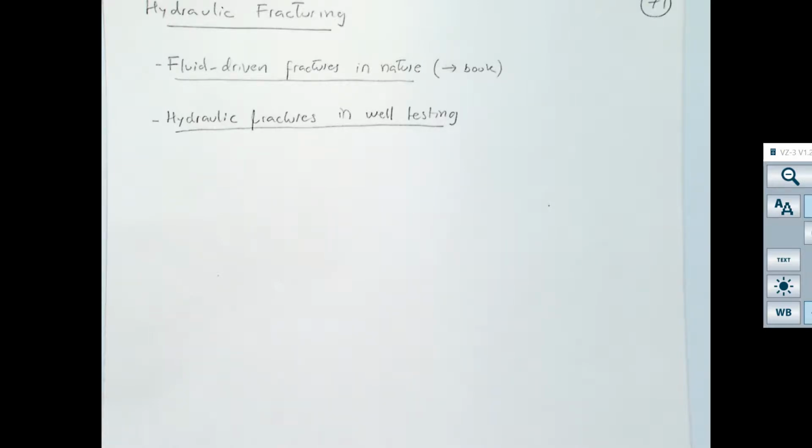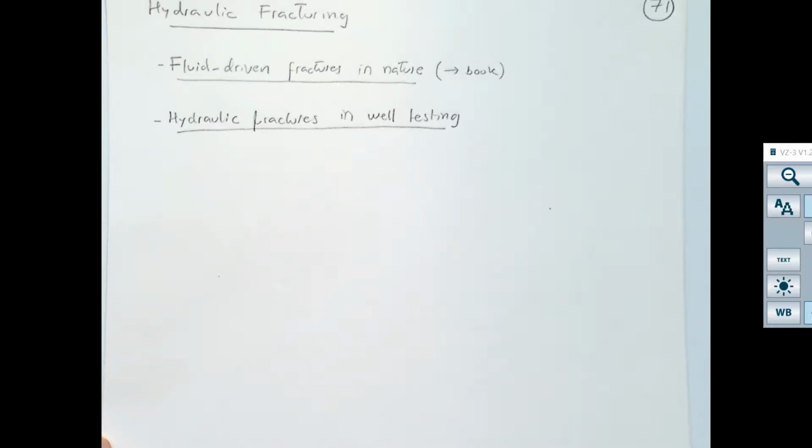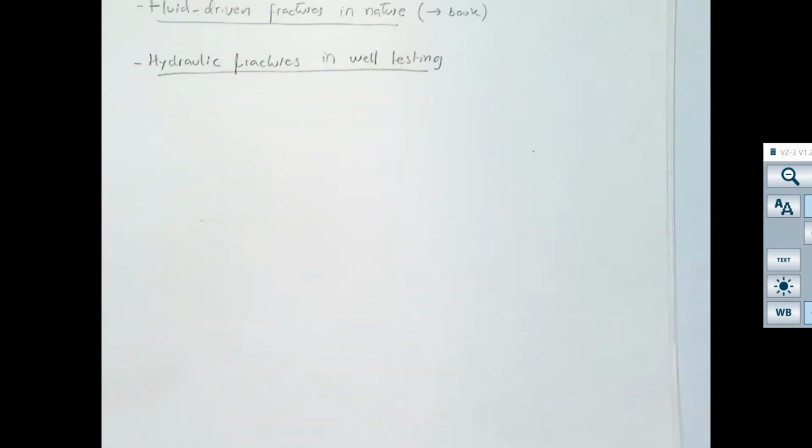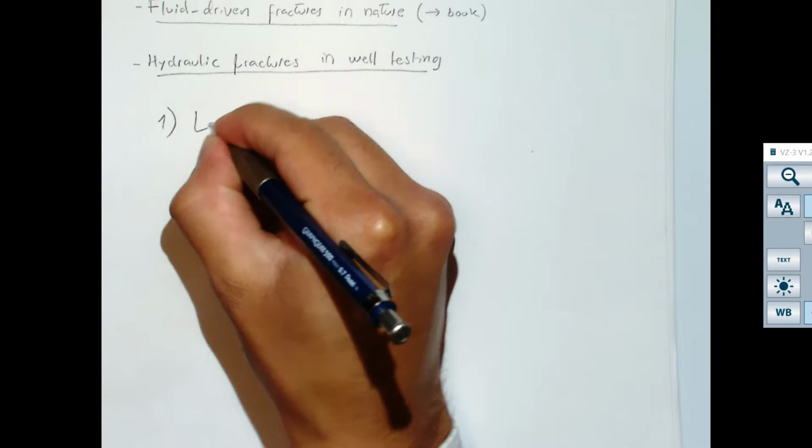That is very useful for drilling stability, for fault reactivation, and also for hydraulic fracture design. But we're going to see later on that some of these tests are also very useful for safely injecting fluids like brine or gas or CO2 or anything you may inject in a formation. Okay, so we're going to start with the first one, which is the leak-off test.